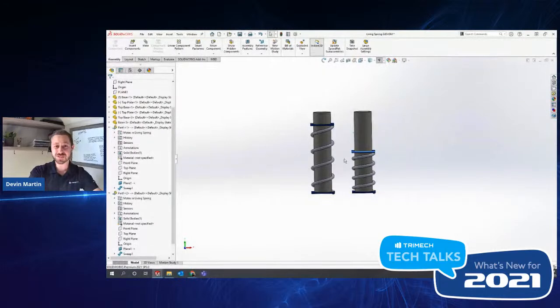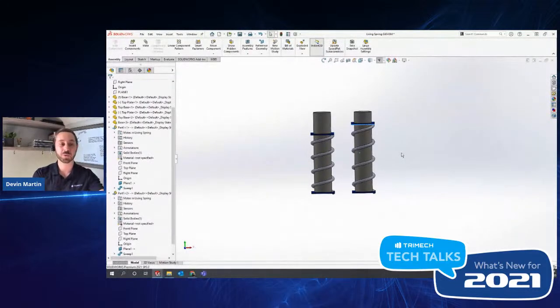This is really cool, and it allows you to have just one spring in an assembly and then use that in the bill of materials. So rather than having 4 springs in the bill of materials all at different compressions and whatever that might be, this lets you quickly create a spring using just a line and a circle, add this into your assembly, and use that one component multiple times in order to really effectively get a nice living spring inside an assembly.